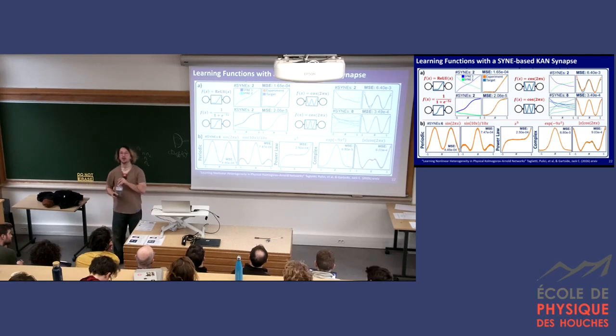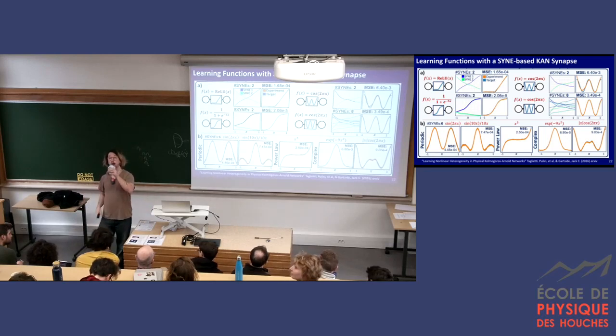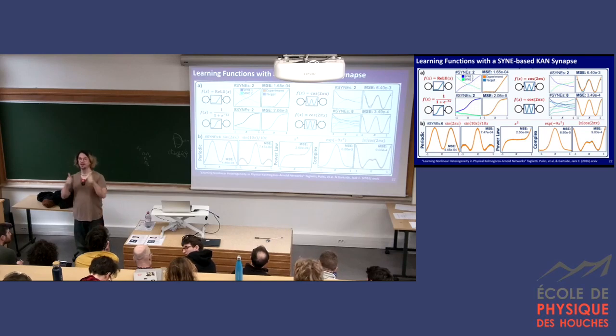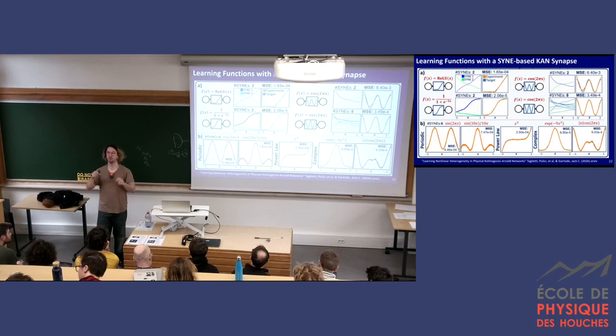Hey. So for each two tunable parameters, you just train it on the digital twin with just backprop. Exactly, super simple backprop. Then we get these voltages, and then we just transfer them. So we're measuring it with an FPGA controlled source measurement unit, and that applies it to the real system.